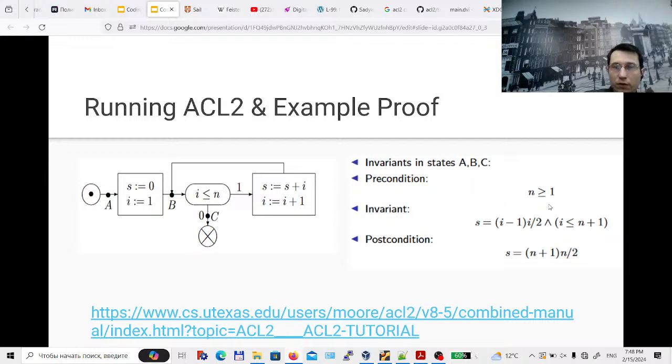For another approach, for example, model checking, we have a simulation of some expression, for example, an invariant, and we try to dynamically execute this model to check the statement and verify it is true for many values, for example, for millions of states. But using an analytical approach like theorem proving, like ACL2, you are able to verify infinitely many states of programs and hardware.